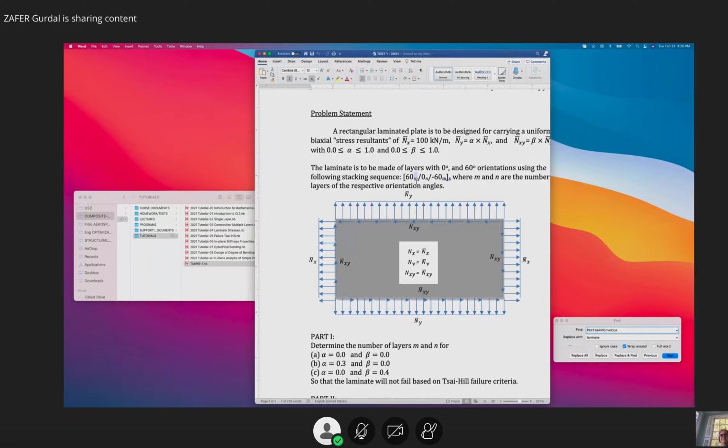Now, the only missing thing is we have looked at the stresses for the bending case. We're going to look at some stiffness requirements for the bending case. And what I'm going to do to make this interesting is go over a study where we asked, can we find laminates that are really isotropic in bending stiffness?